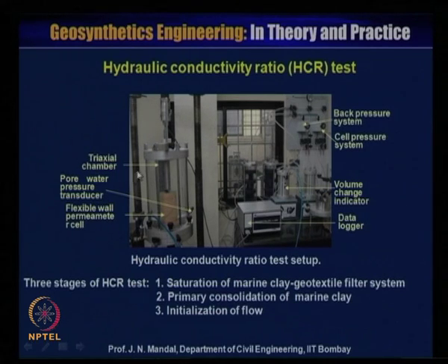Here is a triaxial chamber, this is the pore water pressure transducer, this is the flexible wall permeameter cell, here is the volume change indicator, here is the data logger, and this is the backup pressure system, and this is the cell pressure system.